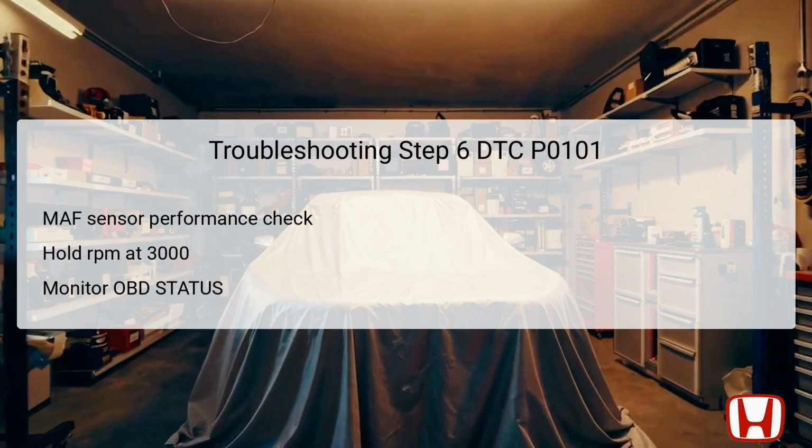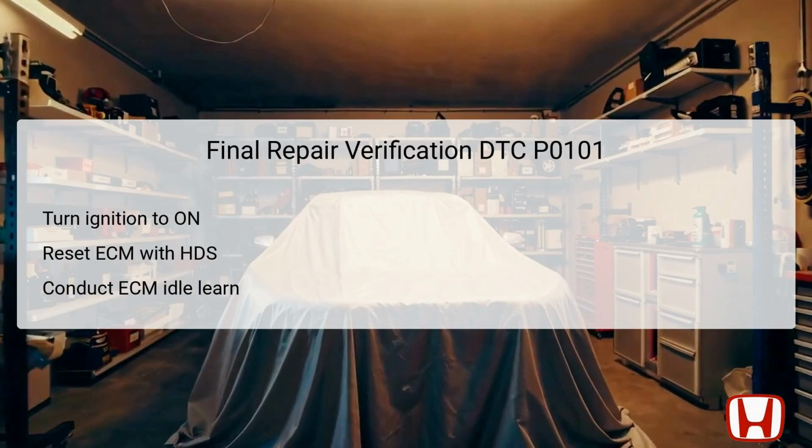If the code indicates a failed status, replacing the MAF or IAT sensor becomes necessary. If passed, you may have an intermittent failure, suggesting that more detailed checks of connections and terminals are warranted. Final repair verification is a crucial part of resolving the DTC P0101 code.